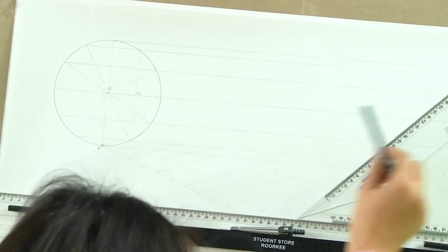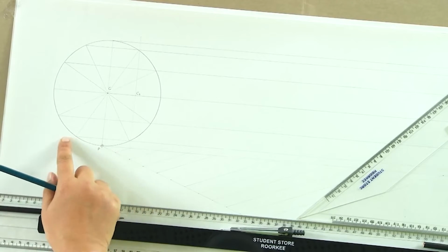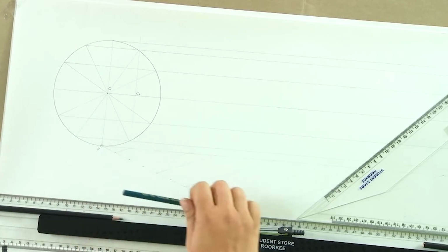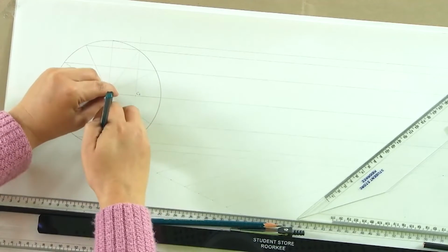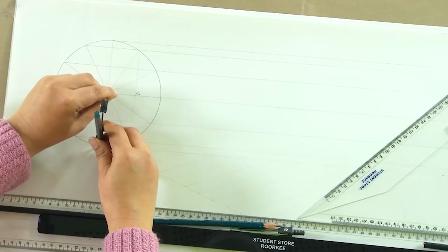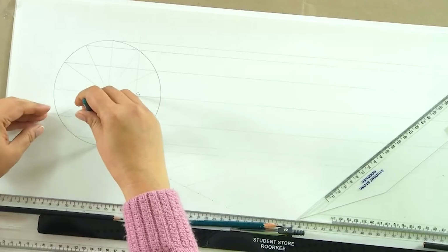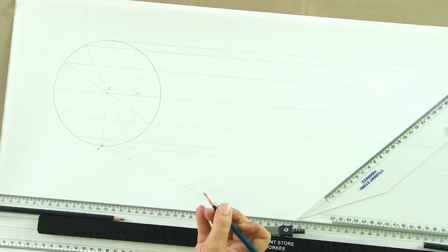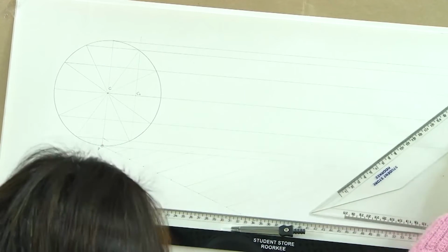Now, how much would that be? So, that is along this horizontal line. So, this P would have come to the position in horizontal, the position which is taken up by this next point. So, what we will do? We will keep our compass at 7 centimeters, which was the radius of the circle, and from C1 we will now mark a point in this line, which is the second line. So, this is where the point P would have moved.